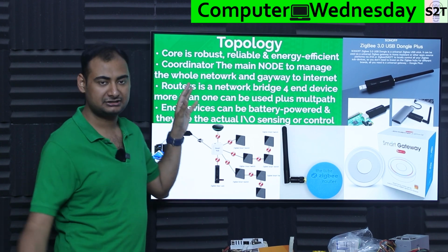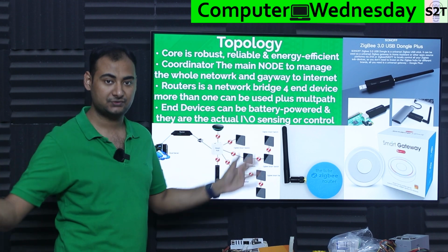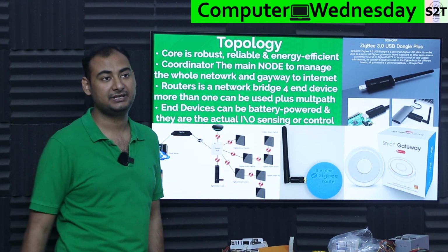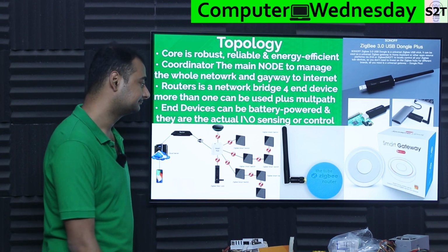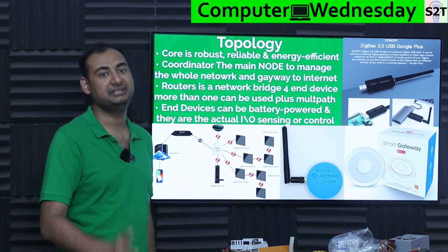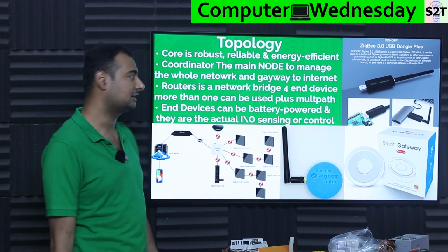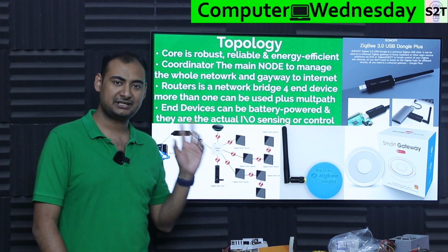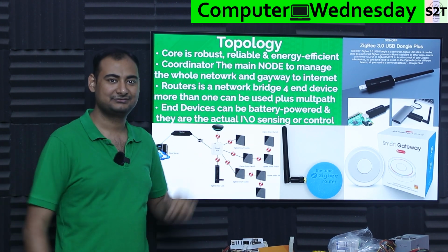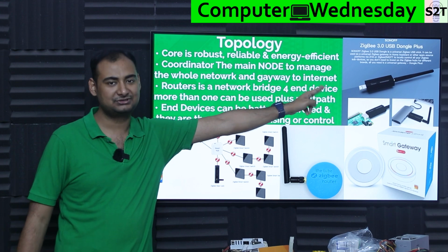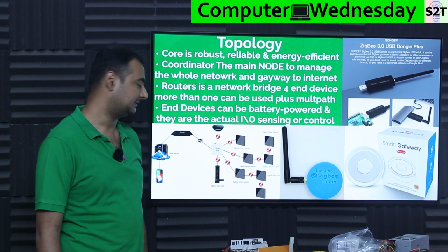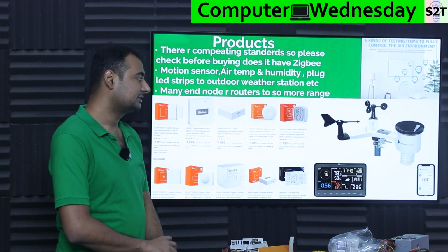So you have a coordinator that collects all the data, a router that allows the network to function, and end devices that do things. These three things allow you to make that mesh network. Now be mindful, not every device is clean cut. Many mains powered end devices would be router only. That's why many times you will have a hard time finding people just buying routers. You may already have more than enough. So that's the topology aspect of it. So what were the products?